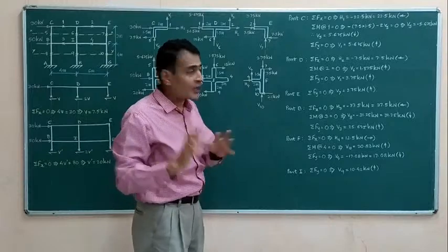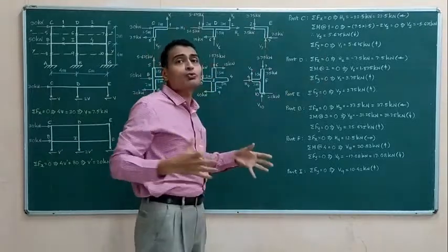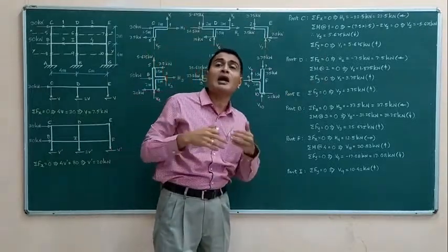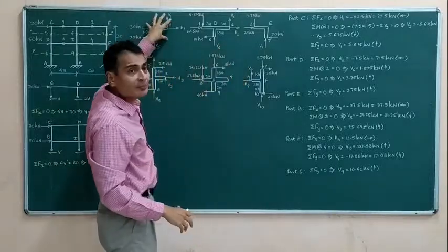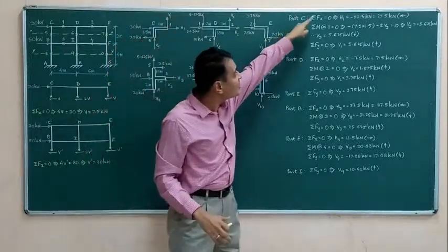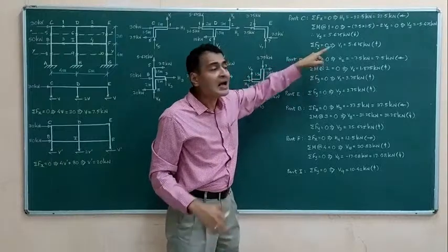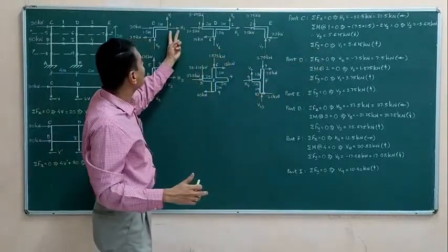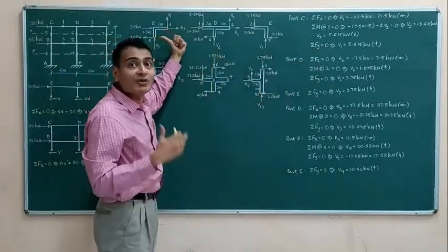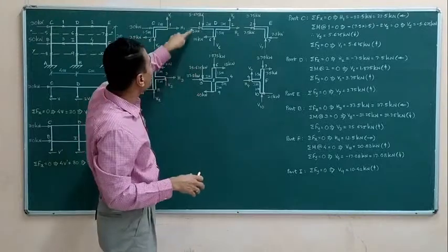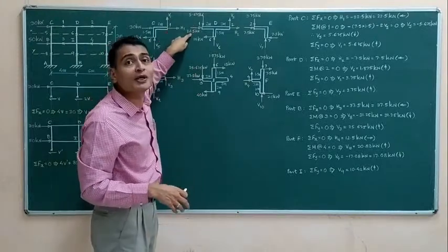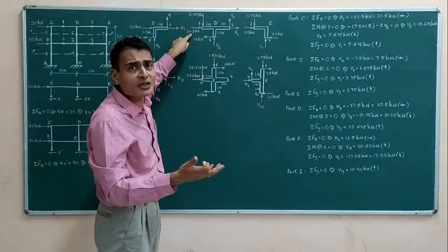Mind you, right now everything is in front of you. The code is already written, but how have I progressed over it? I had drawn this diagram. I wrote this and calculated this. I came to know that H1 was actually leftwards with value 22.5. Then using that, I have drawn this as rightwards 22.5, equal and opposite.